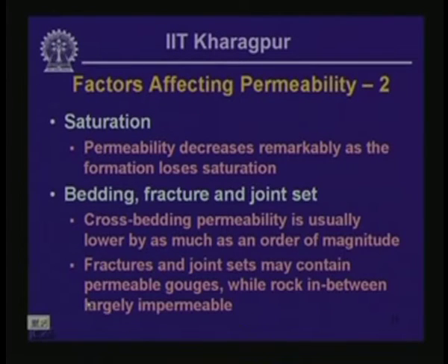So some more factors that affect permeability. Saturation ratio is another factor that is going to affect permeability, and in fact permeability decreases remarkably as the formation loses saturation, because the pore space becomes occupied by non-interconnected volumes of water, and these non-interconnected volumes of water are relatively difficult to mobilize through the interstitial void space.